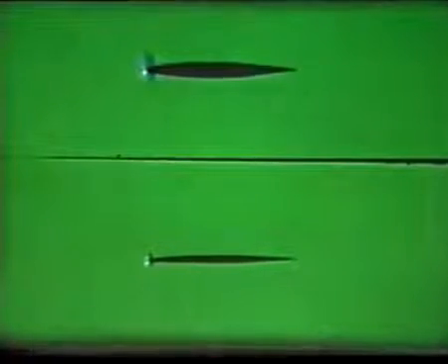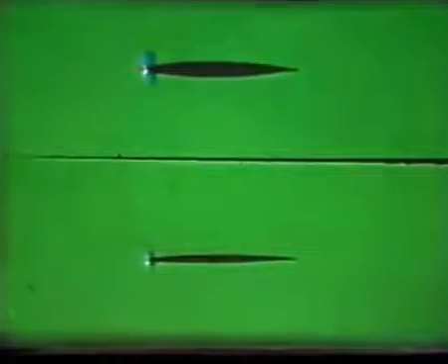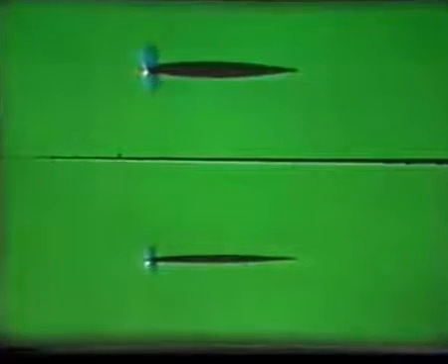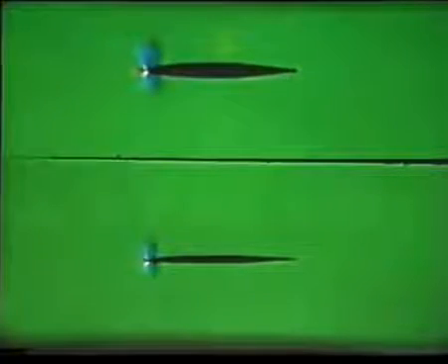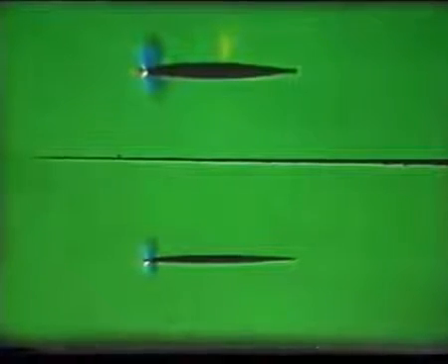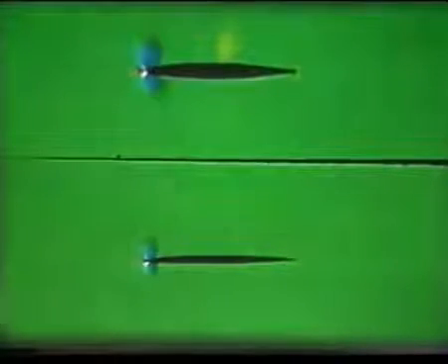These two wings are of the same general shape and at the same angle of incidence. The tunnel speed is the same for each. As it increases, the shock wave forms on the thicker wing at a Mach number of 0.8, but not a sign yet on the thinner one.